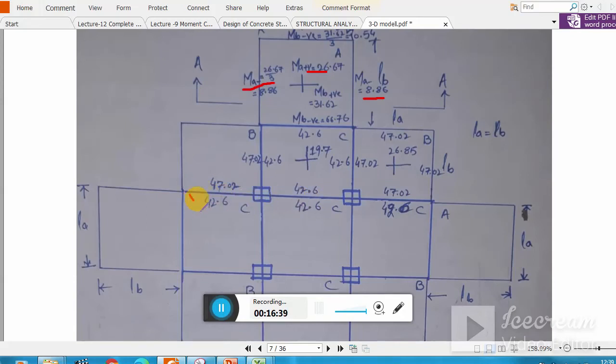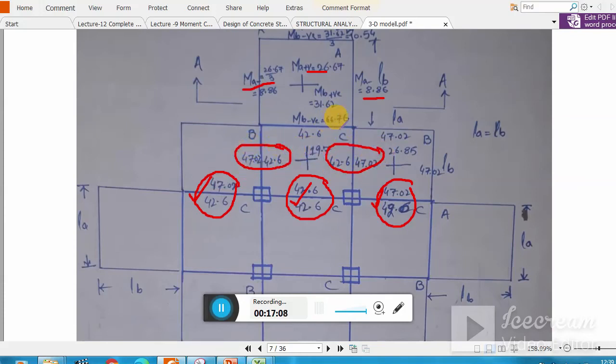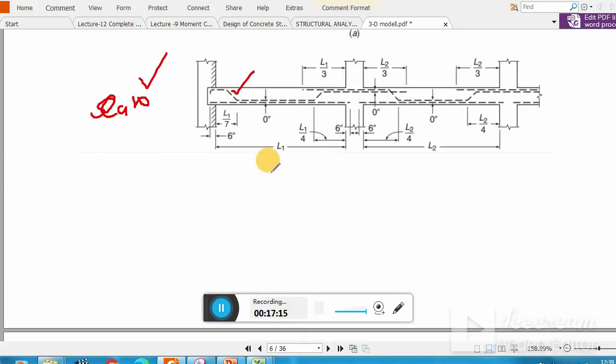Remember, looking at the beam positions, the negative regions over the beam in the slab have the maximum moment. Remember this one. Clear? Because it will also be doubled, these are the critical regions. Similarly, here you see negative moment is dominant. Same case here and same case here. More critical regions, so you have to provide proper reinforcement.